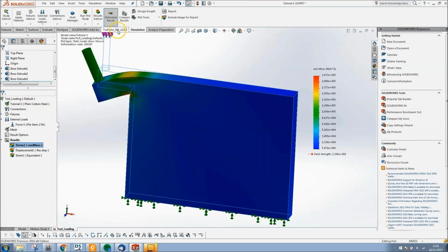Okay. So we've built up our simulation. If you're a user of the simulation module inside SolidWorks, this is completely unchanged, and you work in the same way as you always would. The difference being here, rather than designing and assessing the part you wish to manufacture or complete the design, you develop a design space of where the material could be.